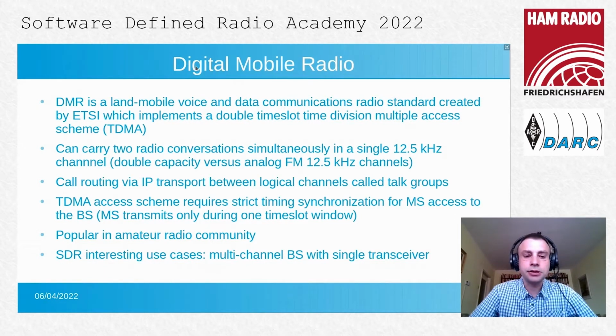This standard also offers caller routing via IP transport between logical channels called talk groups. And because it uses the TDMA access scheme, it requires some strict timing synchronization in order for the mobile station to access the base station, which means that the mobile station only transmits during one time slot window, with the possible other mobile station transmitted in the other time slot served by the base station.